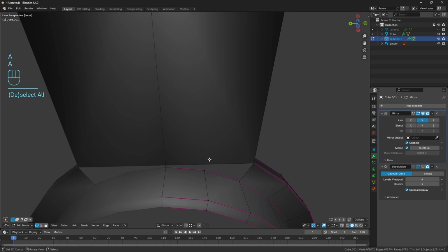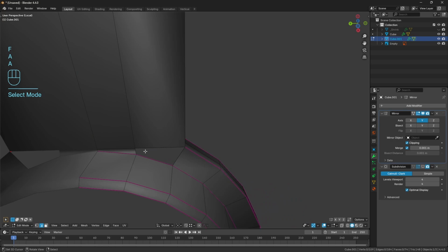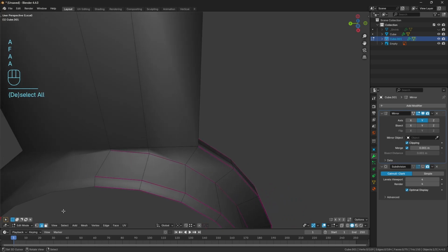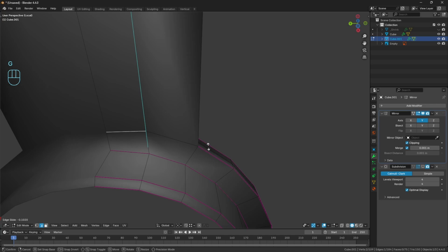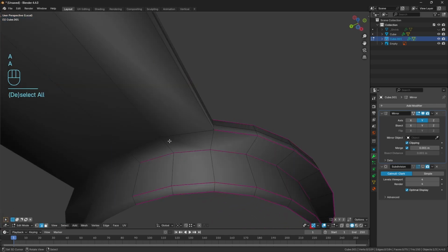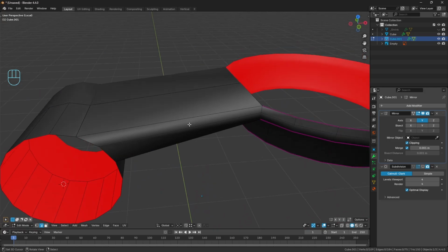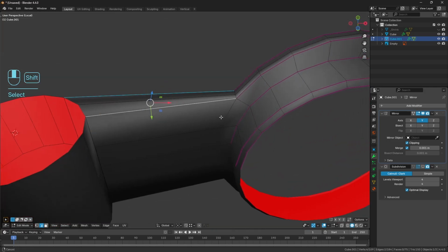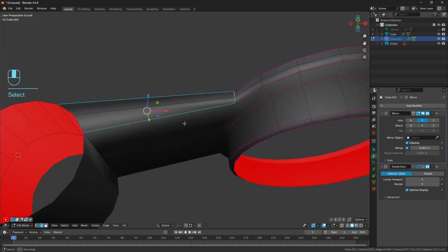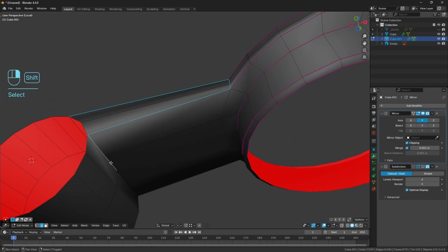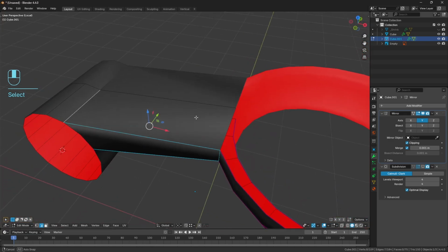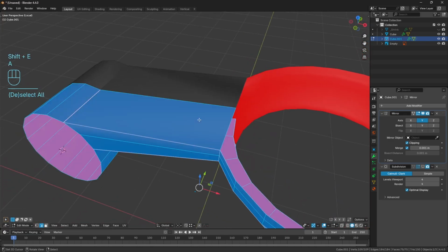And let's Control R, we'll add in another loop through here so we can start to build out a set of faces at the bottom. Like that, and I'm going to do an edge slide here to make this conform more to that circular shape. Maybe we could have left those faces from before, but oh well. And we can start to crease all of this up as well. So I need to crease it along the bottom, on there.